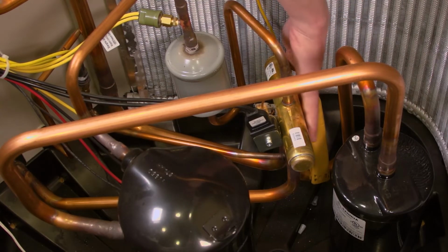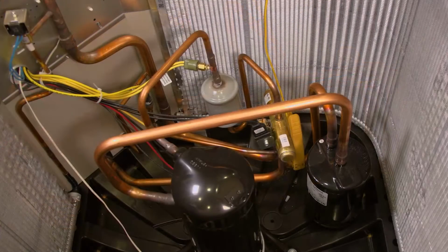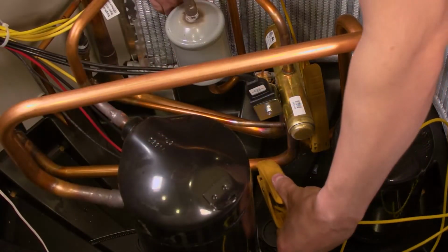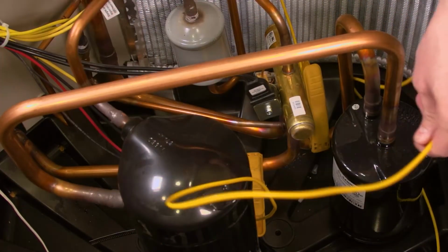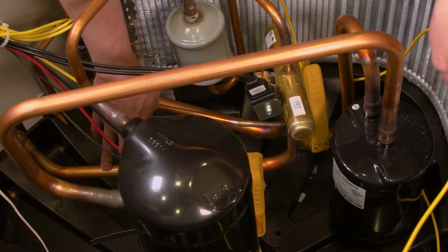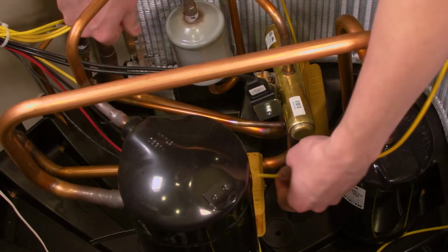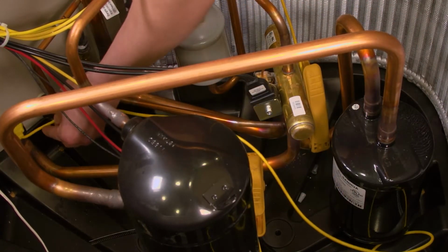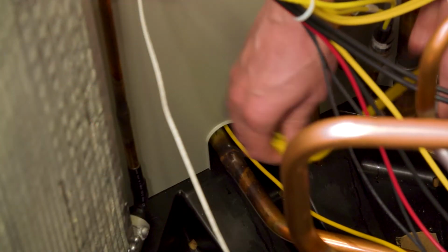So this comes in through the bottom of the valve, and that's our middle line. And then per our test here, we're going to test this unit in cooling mode. So what we'll do is we'll take this line here, put our clamp amp on that. So again, this line goes out to your common suction port on the unit, and then what we'll do with our wires here, we're just going to feed this through where our refrigerant lines exit the unit. And then we'll re-hook into our gauges.